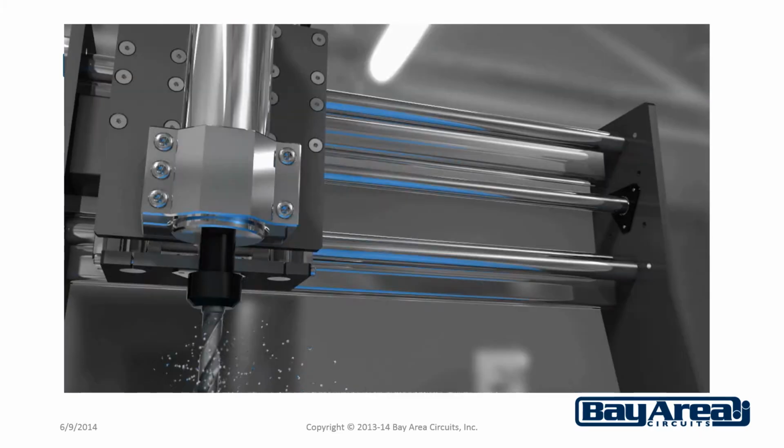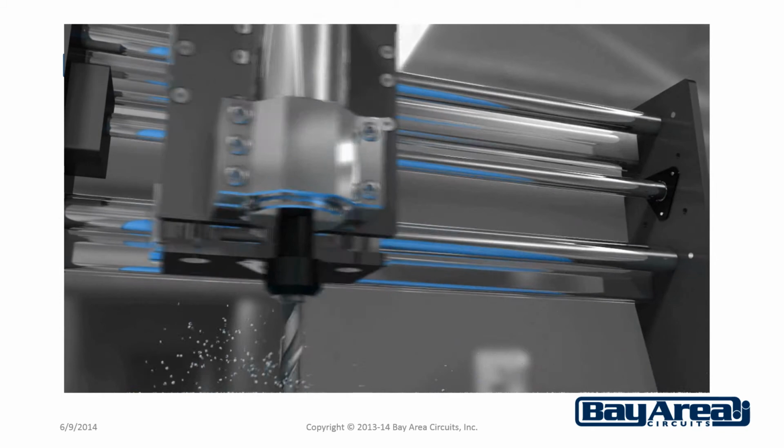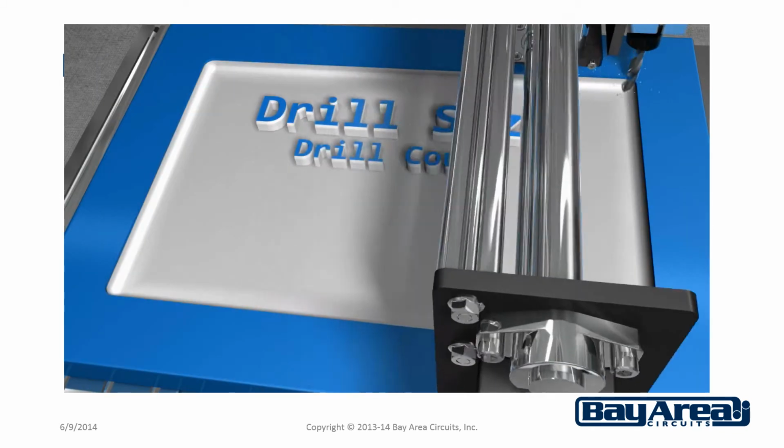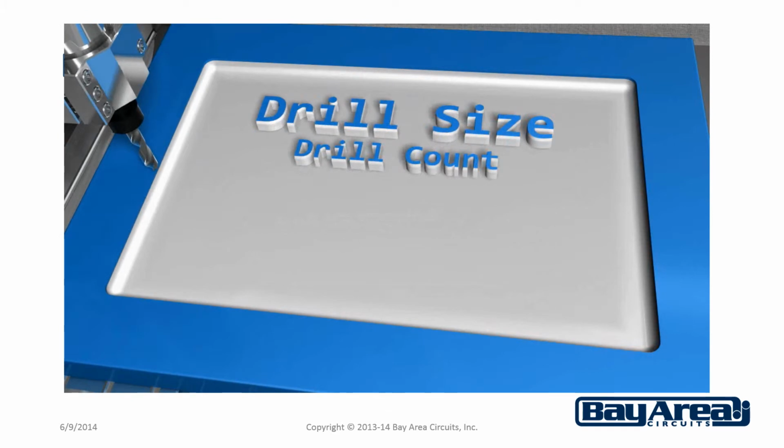Key factor number 4 is drill size and count. When the hole size gets under 15 mils, the cost can increase 5 to 10%. Also, a large number of holes can increase the cost by that same percentage as well. The manufacturing process has to be adjusted with smaller hole sizes and large hole counts.